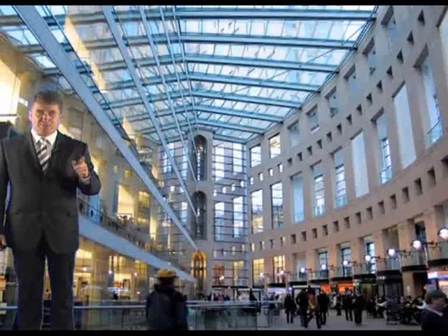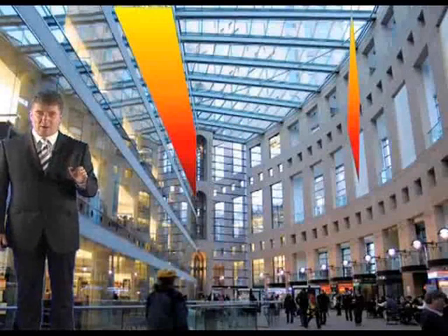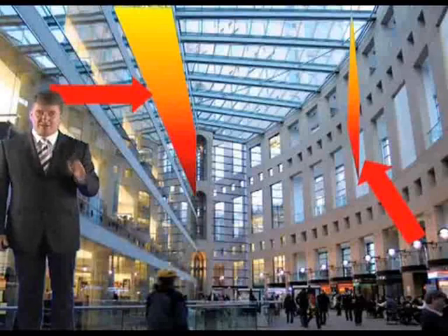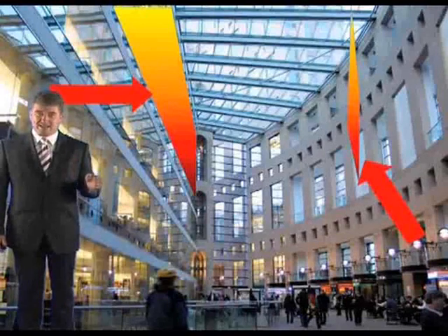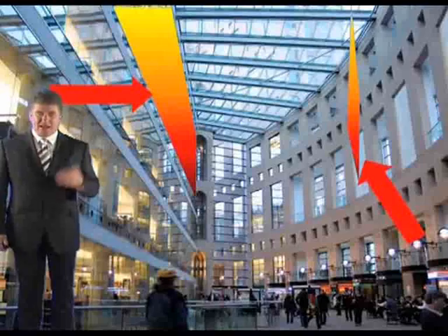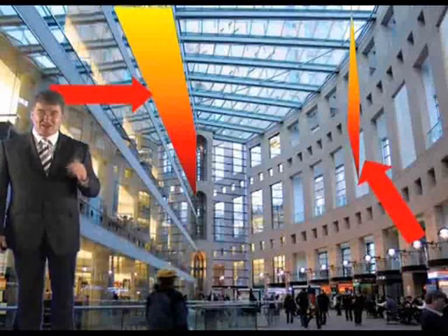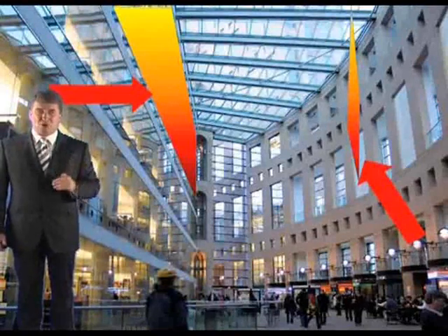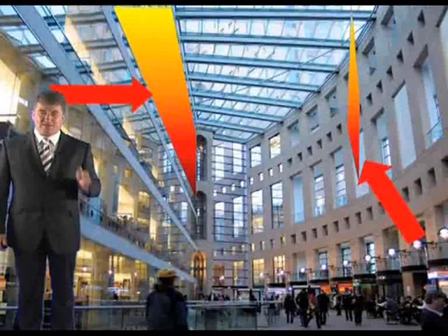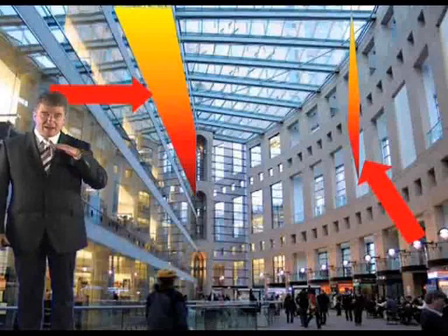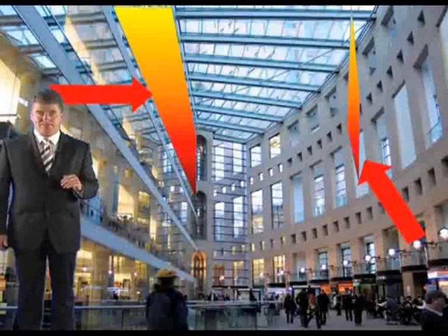First of all, there must be some means of forming a smoke reservoir to prevent the lateral spread of smoke, which could result in excessive loss of buoyancy. Generally speaking, malls with high ceilings or roof lights will allow a deeper smoke reservoir and hence a more effective smoke ventilation system than in very low, narrow malls.